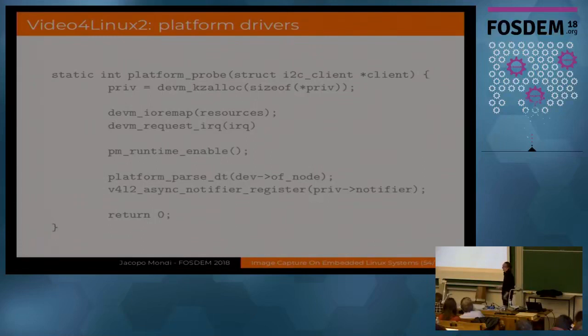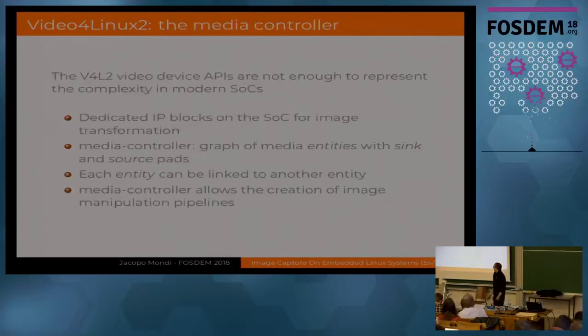You use that framework to register notifiers that wait for all of that to be available, and once they are, the driver knows that user space can start calling functions and actually use the video capture interface. So this is the most simple use case you can have. This is just a sensor and a receiving side, nothing else, that takes data and writes it to memory, and user space fetches it and does whatever you want.